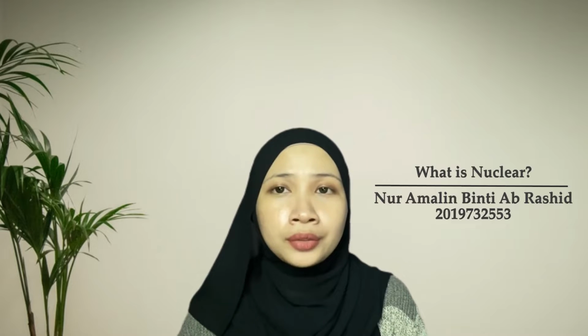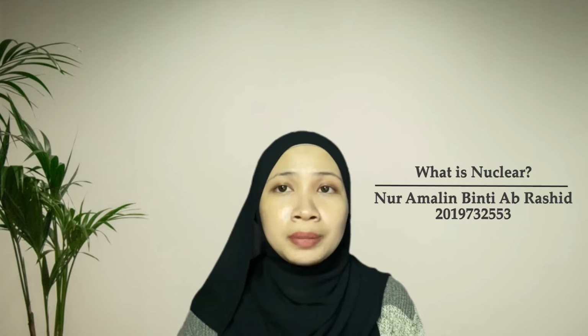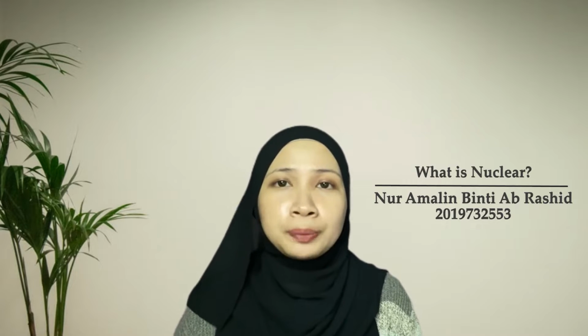The light water reactor is a power reactor that uses ordinary water as both coolant and moderator to keep the system cool. There are two major types of light water reactor, which are the boiling water reactor, known as BWR, and the pressurized water reactor, known as PWR. The difference between BWR and PWR is the boiling method for steam. PWR constitutes the large majority of the world's nuclear power plants.